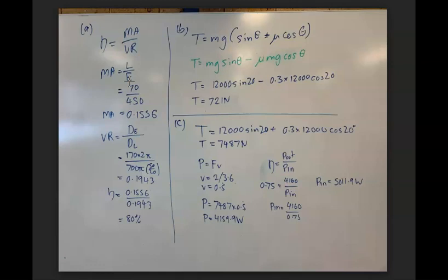In this case, for bikes, because I have put a bike in every question so far, it's a reasonable assumption that if you're watching this in the future I'm going to put a bike in the next one, you'll get a mechanical advantage that should be well and truly less than 1, right? Something less than 0.2. The velocity ratio is the distance traveled by the effort divided by the distance traveled by the load. I didn't look that up on the formula sheet, and I don't really remember it, but how I do it is I just do mechanical advantage and I reverse the letters. That works for me.